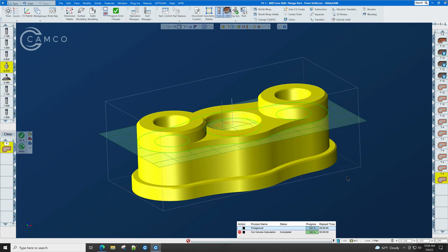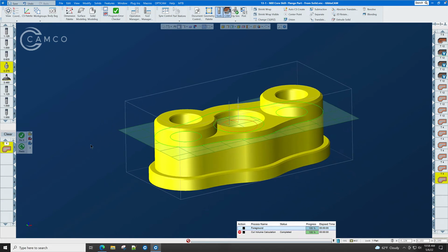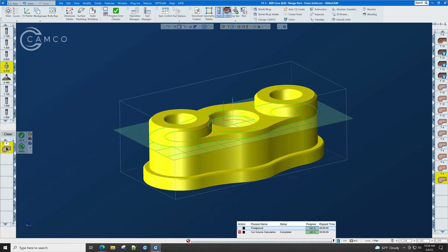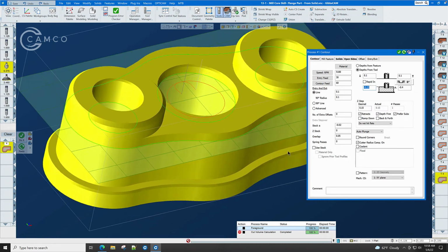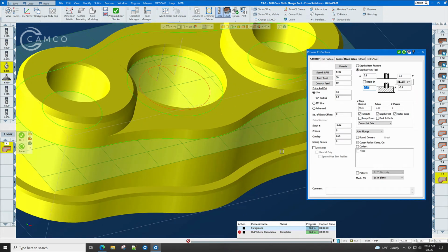We now have one more chamfer to cut down here on the bottom, and we're going to use the exact same technique that we used before. We're going to set this to the top of the surface. We're going to use the Alt key interrogator to get that -1. And remember, this is -1, minus 0.150, because we don't want the side of the cutter to hit the side of this part. And the chamfer is -20.